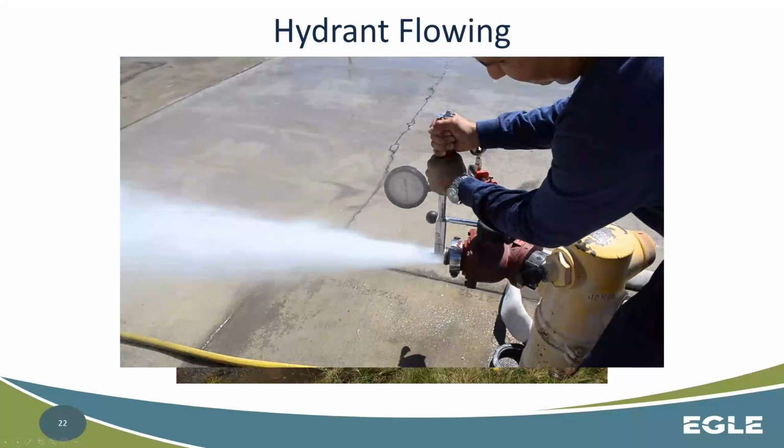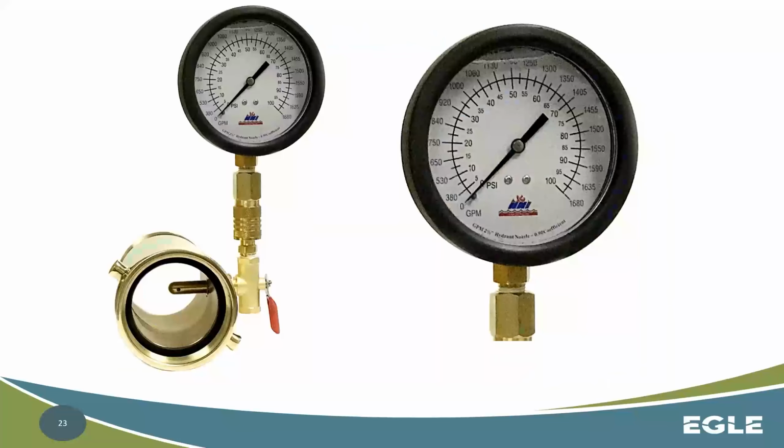So with that static pressure gauge and this pitot blade, which gives you a pressure reading right at the orifice, if you hold this in line properly, you take these readings and you can calculate what the flow is off of this meter. I will say that there's some calculations involved there, but we're not going to go through the calculations in this course. Oh, no, sorry, I'm getting ahead of myself.